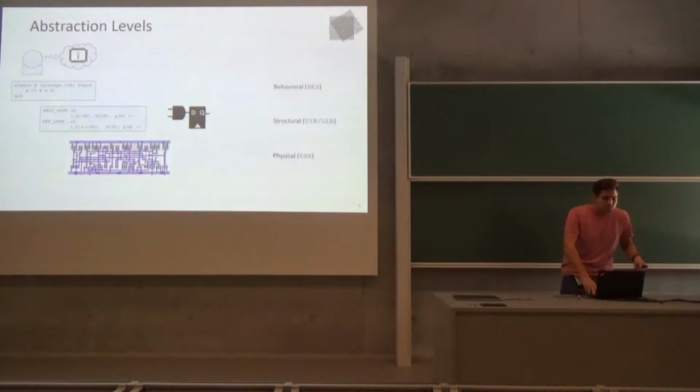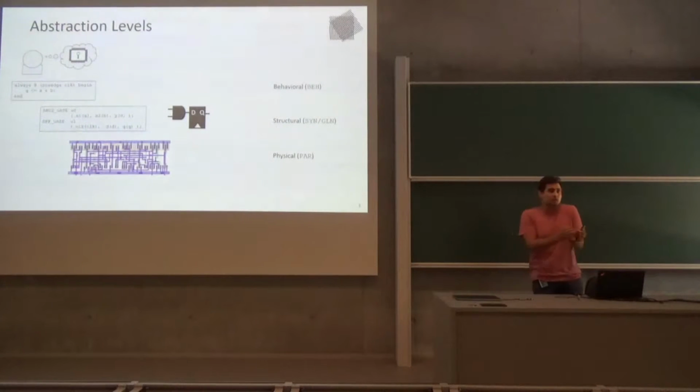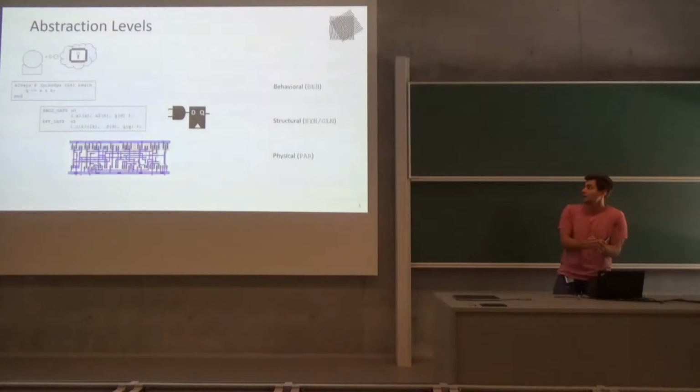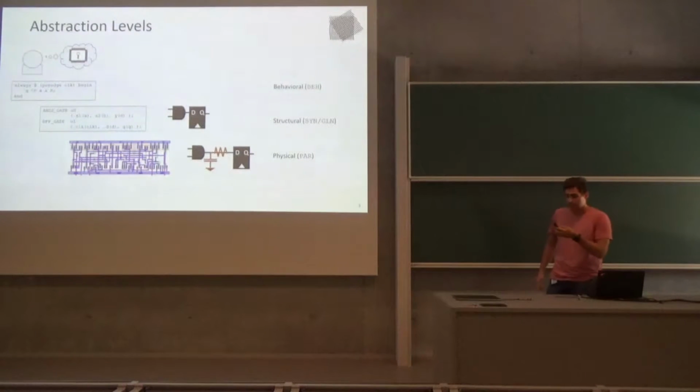from a library. Then, because in the end you want to make a physical chip, the next step in your output is something like this. There's actual layout with all these layers on the chip, but since you would have to work with SPICE or analog simulations at this point, there's been decades of work in the EDA industry to take these little interconnections and the effects of layout and model them as resistors and capacitors. This is called the physical level.